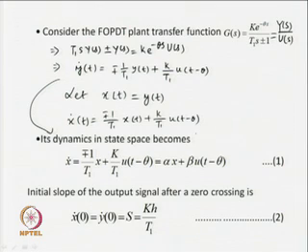Let us assume x dot (t) to be expressed in the standard state equation form of x dot (t) is equal to alpha x plus beta u(t minus theta), where alpha is now minus or plus 1 upon T1 and beta is equal to K upon T1. Why are we writing this in the standard state equation form?